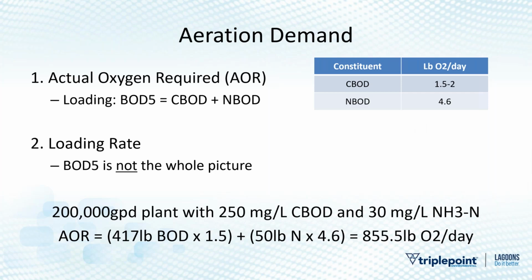So for those of you that may not have heard the story, BOD5 is simply a measure of what happened. London, which was one of the earlier modern civilizations, realized they're putting too much waste into the Thames River and it stinks and the fish are dying and we don't like that. So they studied it and they figured out there's an oxygen demand of the waste you're putting in. And BOD5 comes from the fact that the Thames River flows for about 5 days from London to the ocean, and they didn't care about it after that.